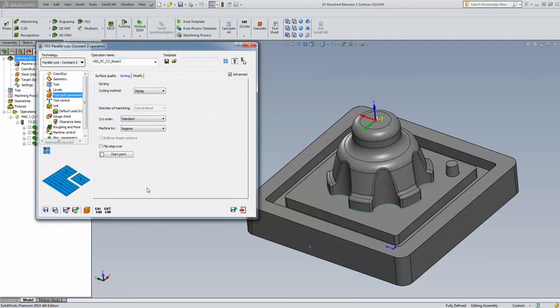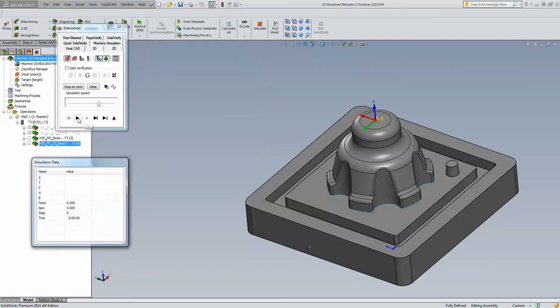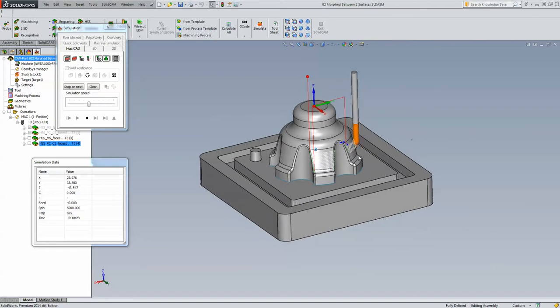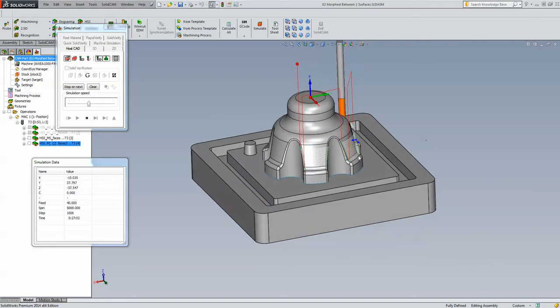Let's take a look exactly what happens over here now. What's going to happen is very simple. It's going to work on each region and then go to the next area. Okay? So this is actually a much better way to work in this particular case. Working by regions is also a good way to change the actual toolpath itself from jumping up every single time. It does each surface and then moves on to the next surface.